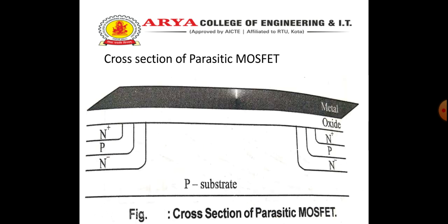Now, cross section of parasitic MOSFET. Formation of parasitic MOSFET: if we add an insulating layer and a metal line over the substrate but do not contact both transistors, a parasitic MOSFET exists. The collectors of two transistors act as source and drain of the MOSFET and the metal line acts as the gate.